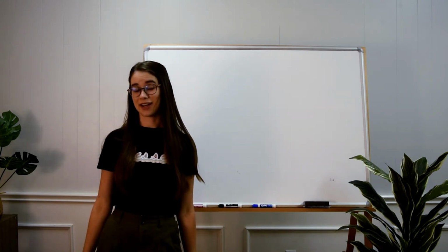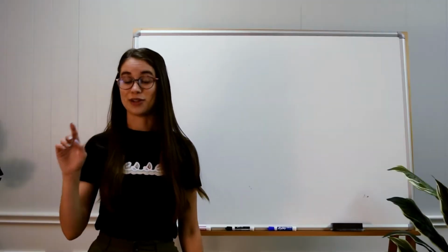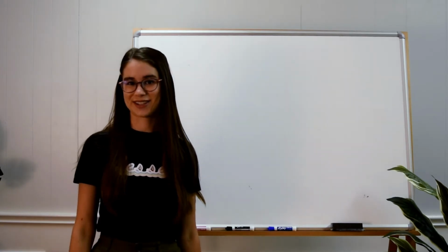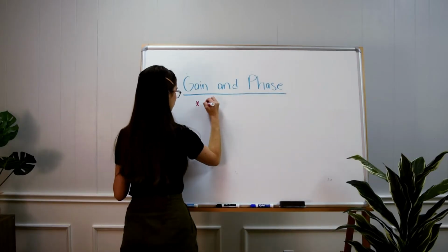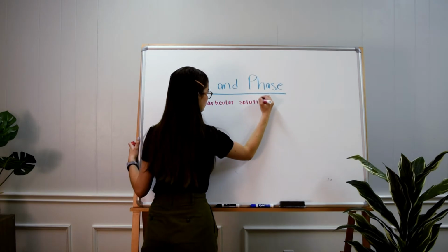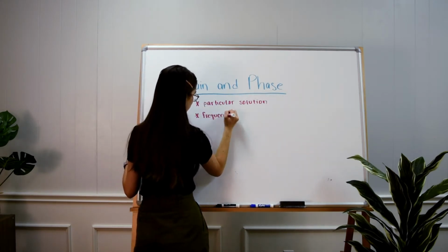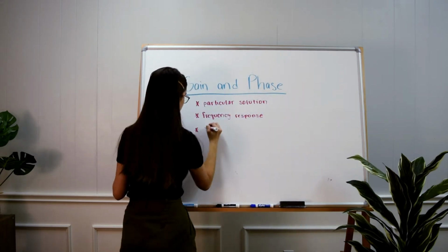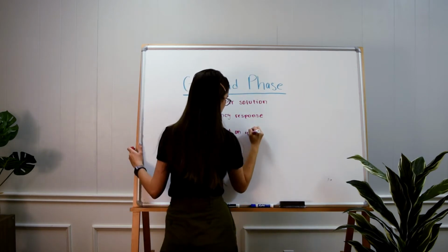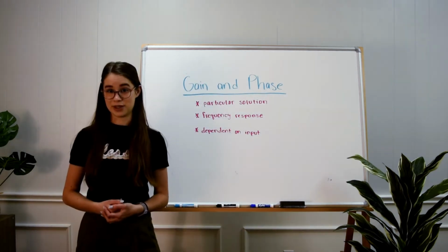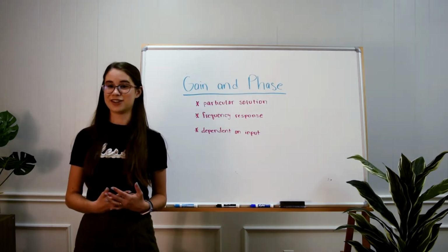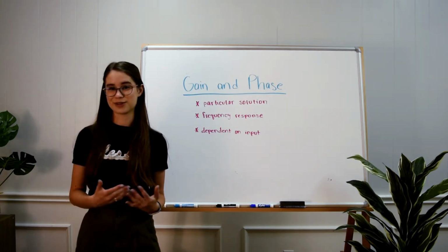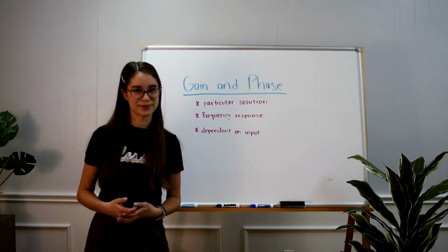Today we're going to be calculating gain and phase two ways, using Euler's method and transfer functions. Gain and phase are part of the particular solution to our system differential equation. Now, they are dependent on the input, unlike our homogeneous solution. And they are key players in our good friend frequency response, so like sinusoidal inputs.